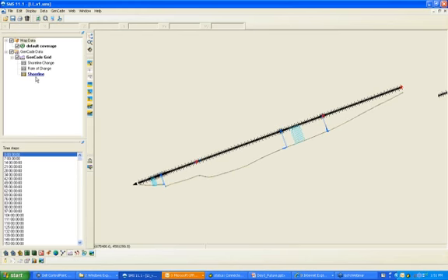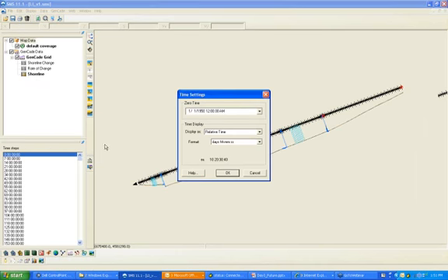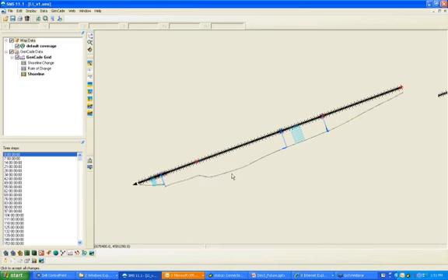So in this case, you're going to see that we actually have time steps that are not referenced to the date. So we're going to go time steps. We're going to right-click, and we're going to go to time settings. And now we have the 0 time. I'm going to change this to January 1st, 1983. I'm going to go and change display as to absolute date and time and click OK. So now we have actual dates.